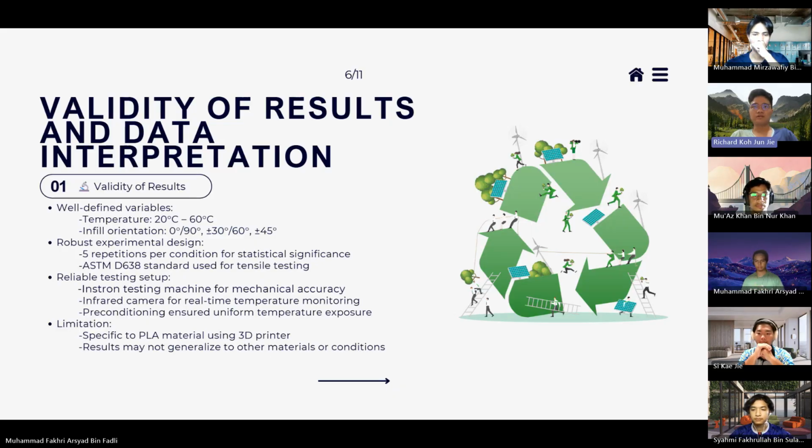Besides, they also followed the ASTM D638 standard using an instrument machine, and the temperature was carefully controlled with an infrared camera and preconditioning steps to ensure uniform heat distribution. However, the external validity is limited since the findings are based on PLA products printed with 3D printers, so the result may not apply to other printers or materials.